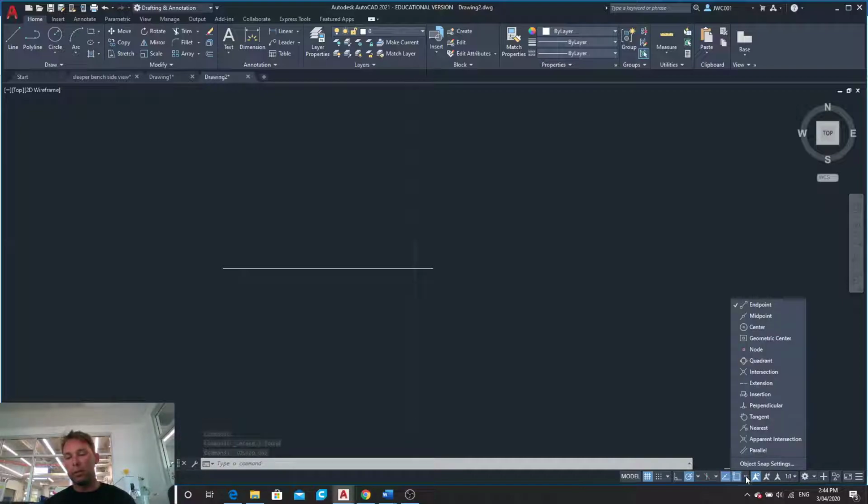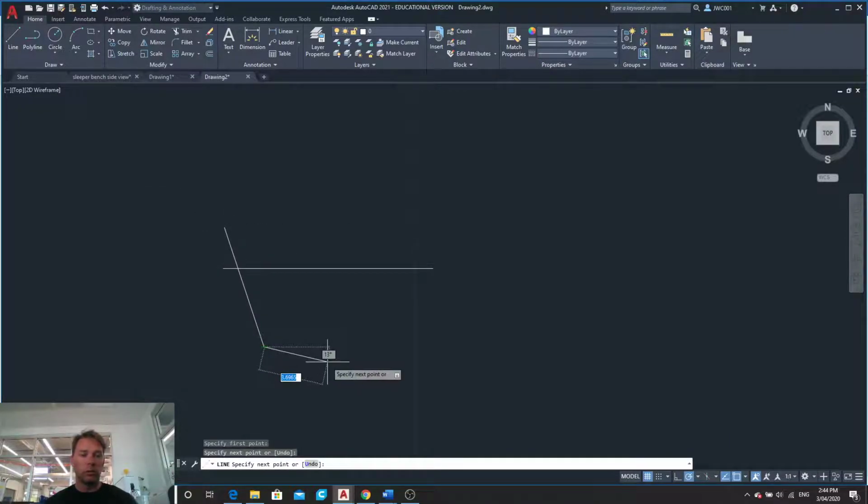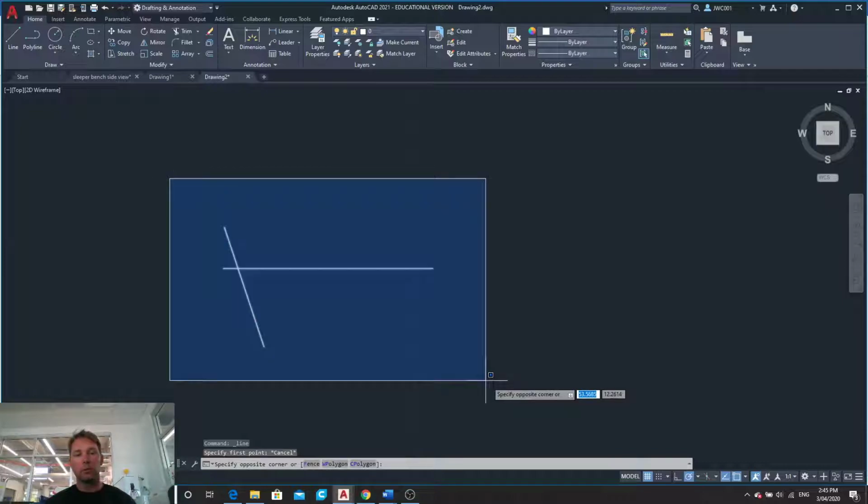And on my drop menu, I can select where it locks into. So I could draw from a midpoint, I could draw from an endpoint, I can draw from an intersection. So let's say I drew 2 lines. I can now draw a line from an endpoint. See how it's highlighted green? Or that endpoint, or that intersection, that's also highlighted green. I could draw from a midpoint for my line, or an endpoint, or a midpoint from this line. So that comes in really handy.